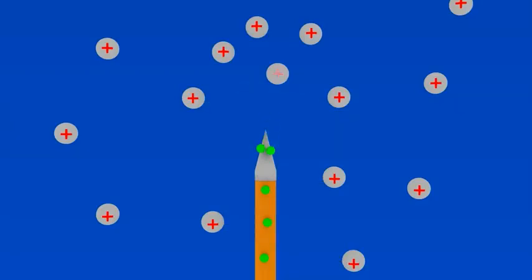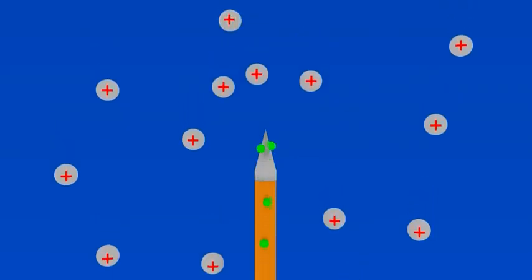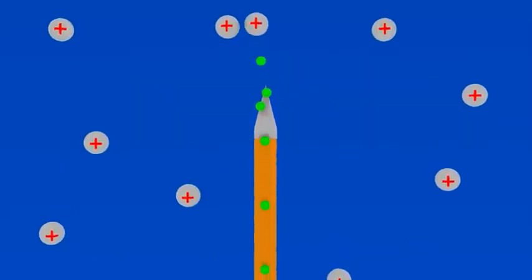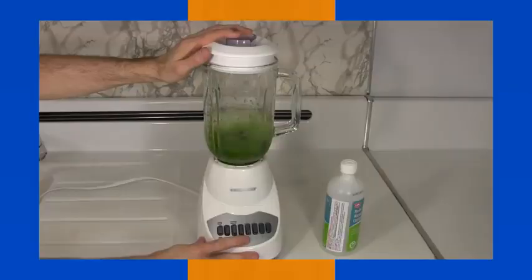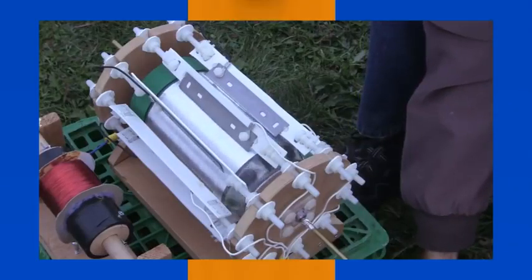It's strong enough to remove the negative electrons from the sharp point, where they neutralize positive ions. But due to the voltage, there are fresh positive ions moving downward and fresh negative charges coming up from the wire. We now have electricity flowing through the wire. The electric current in that electricity is very weak though. We didn't measure it, but from my experience with electrostatics, I'd estimate it in the low microamps, or more likely even lower. That's not enough to turn an electromagnetic motor, one like you use in everyday life, but it is enough to turn an electrostatic motor, like this corona motor.